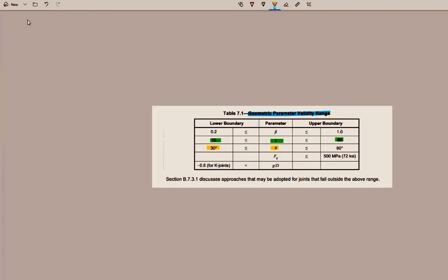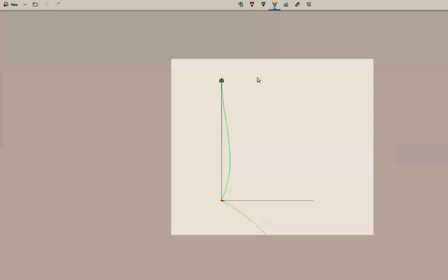What I mean is, if you see here, this is 90-degree it is maintaining, right? And then this also has to maintain 90-degree, and since this curvature goes like this, it is the one curvature, and then this comes like this, so this is the second curvature. So curvature changes at this point. This is the point of contraflexure. Okay, that is when there is a change in the curvature.